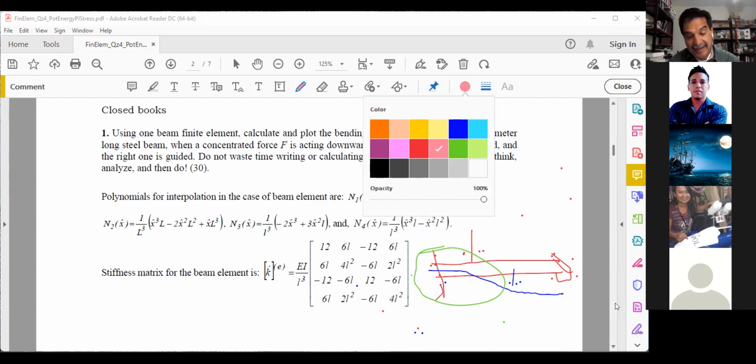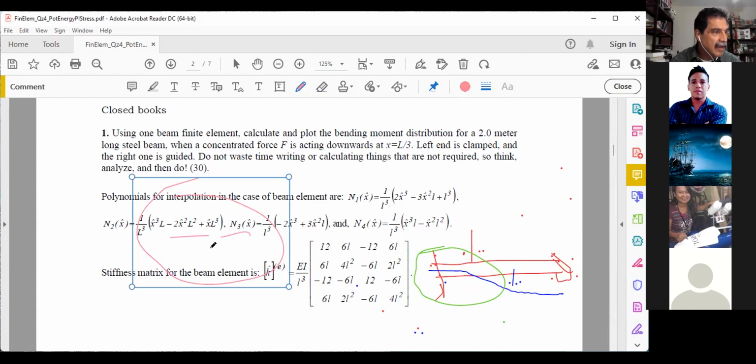And oh man, we're in trouble, people. When you have a sad beam, the bending moment is negative. In this part here, the bending moment is positive because in this part you expect the beam to be smiling. Smiling beam.